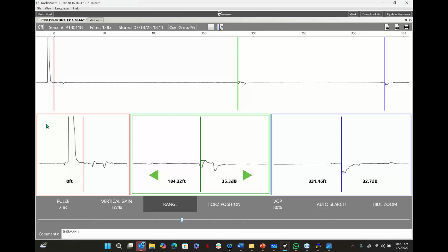I said, okay, we're good. Now, when I get closer to the front over here, the next thing I notice is two events right here, which I'm going to call rather obvious. So if I take my second cursor over here and measure to that, see where my green window is right there? I see something at 4 feet, and I see something at about 8 feet. So I asked them, is there supposed to be something at 4 feet and 8 feet? Did you guys see that before? And they asked me, do you see something at 4 or 8 feet? And I'm like, hey, who's asking the questions here?